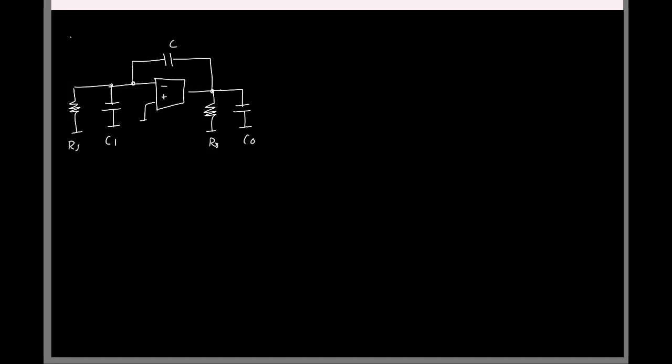Let us say now here I don't have the capacitance C. That is, this capacitor is not there. So do you think the nodes here are uncoupled or coupled? They are uncoupled. So can you comment on the pole we'll have at the input side? That's minus GS by C1. It's not even approximate, this is exactly equal. And what about the pole that will arise due to this capacitor? Minus G0 by C0, right? Because that side is completely uncoupled.